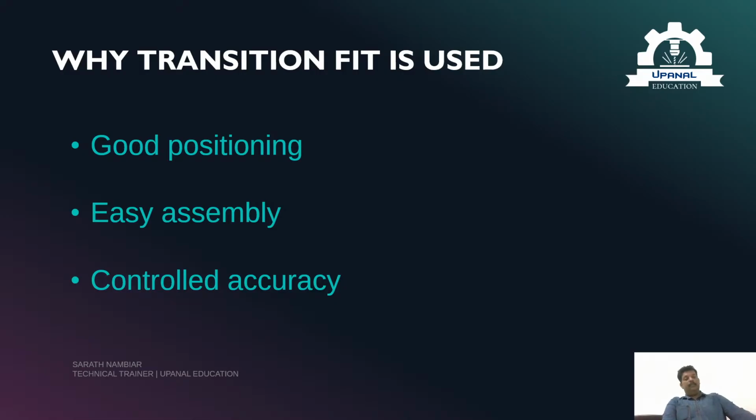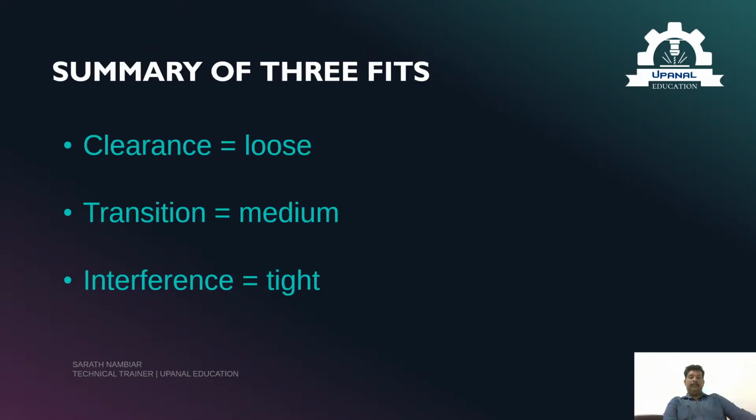That is transition fit. Now, let's summarize the three fits in a simple way. First, clearance fit: always loose, free movement. Transition fit: medium control, sometimes tight, sometimes loose. And interference fit is always tight, which gives a strong connection.